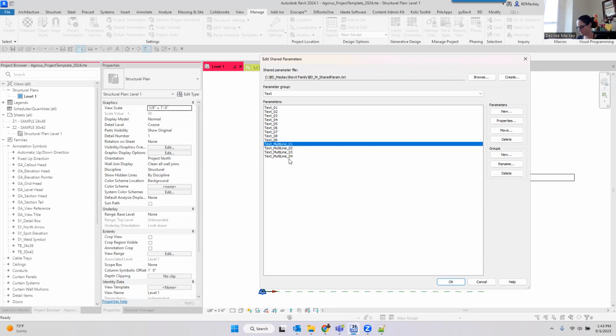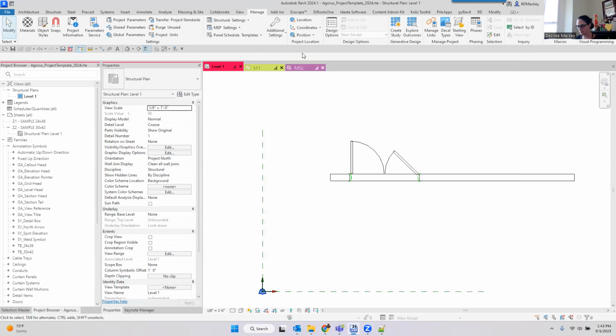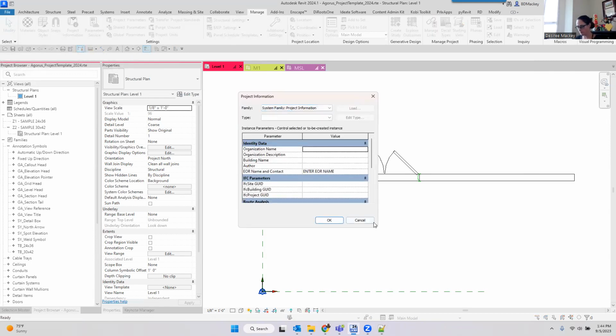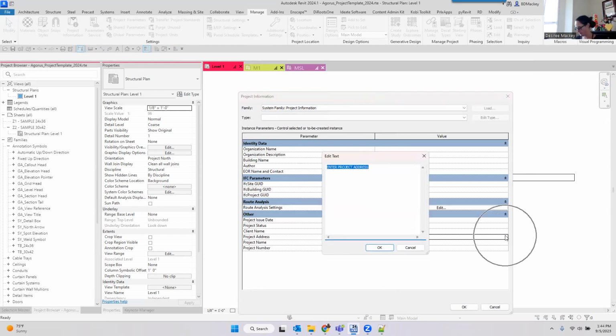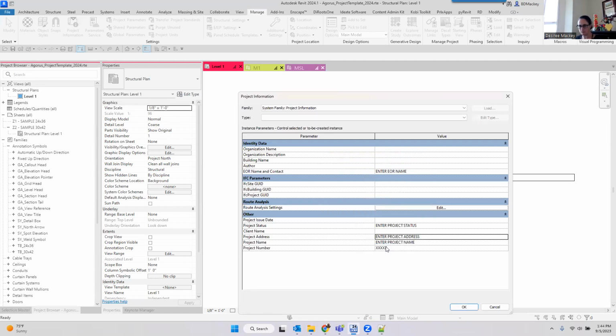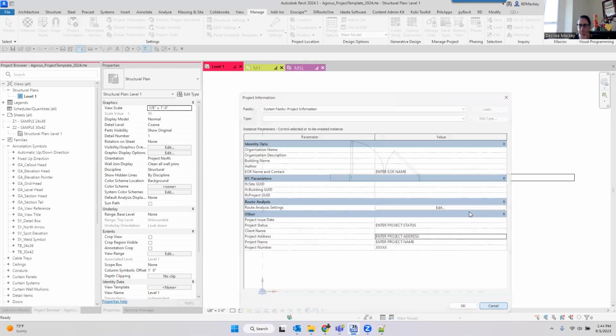I don't see multi-line text used that often when people create parameters. If you don't know what that is, it's like if you go into your project information, where am I? Sheet parameters, global parameters. Right here, the big button, not the little button, and you go to look at the address for your project information. This is a multi-line text. Lets you come up here, hit enter, type in some more stuff, hit enter, type in some more stuff, hit enter. And that's how that would appear in a schedule if you did it that way. So you can control where you want the line breaks rather than just having it word wrap only. So think about generic things for multi-line text as well.